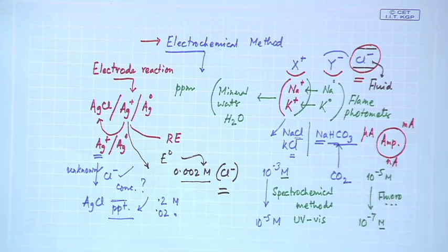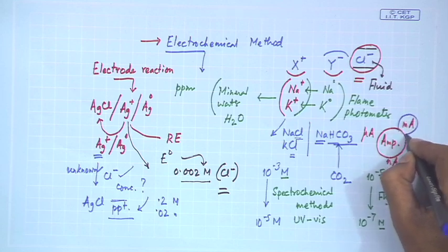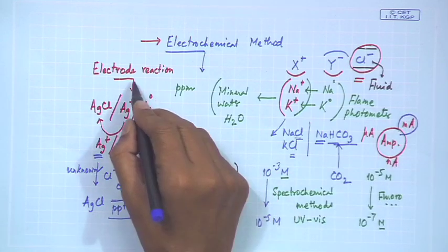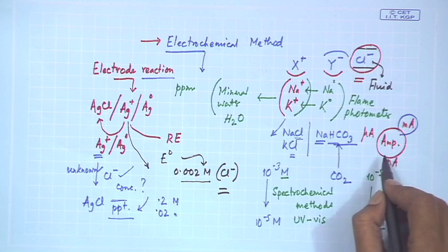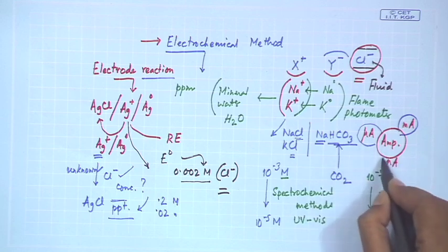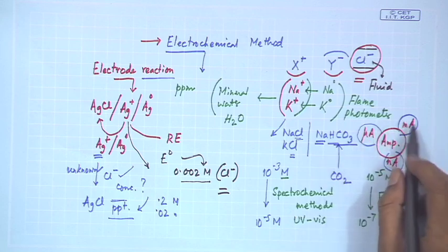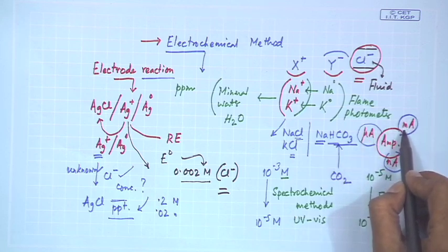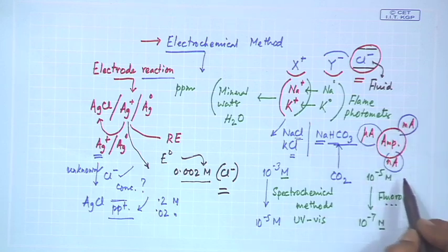So, as we go down, we can have some information from the corresponding electrochemical transducer, which is amplifying the signal coming out from the electrode reaction, because you have the electrode and that electrode is responsible for giving you the corresponding reading in terms of either voltage or the corresponding current. So, milliampere to microampere and then microampere to nanoampere you can handle, because these are all concentration dependent. At certain concentration you get a current in the milliampere range, in other case in the microampere range, or you can go down to a nano level, which is the nanoampere range.